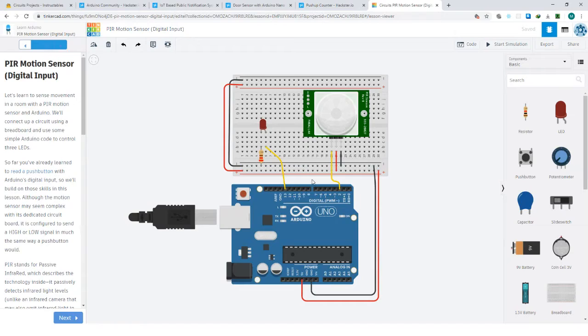I think that's very clear. Remember the pins we are talking about, one is positive and the other one is negative. One is put on the Arduino. It takes the 5 volts of the Arduino, that one in the middle, and then the one at the corner always takes the negative or the ground. You put it on the ground, and then you're good to go. So probably if somebody comes closer, or movement takes place, then this particular LED will just light.